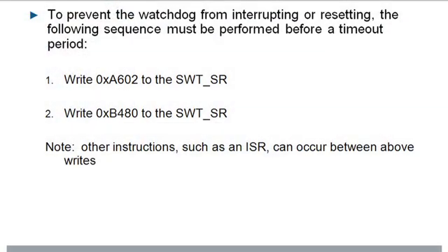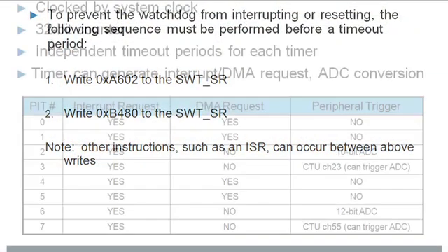First of all, the Watchdog. The Watchdog after reset is turned on. So you can either service it on a regular basis by following these instructions here, or disable it as in all the example code. Okay. There's also window modes you can use if you want to make it more secure. There's locking, unlocking involved also. But just enough said on Watchdog. You've all probably used one before.